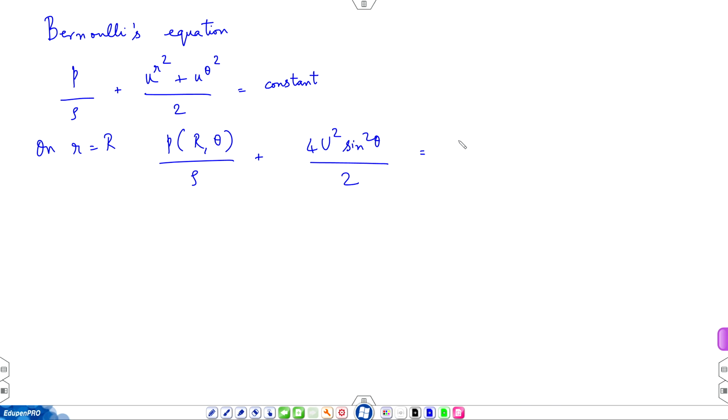Upstream there is some pressure. Now, you may call it reference pressure. If you have an object moving in air, then locally there is an atmospheric pressure. So, that would then be the reference pressure. Some authors, offhand I do not remember the notation used by Frank White, sometimes use the symbol infinity, P infinity. P infinity is far field, and it does not mean light years away. It just means away from the zone of disturbance.